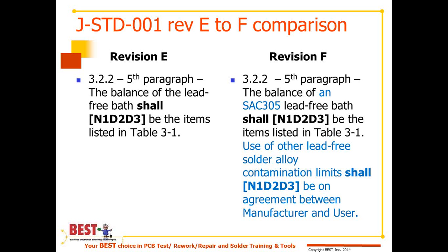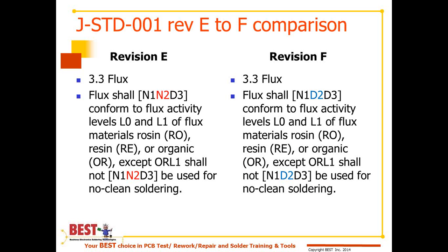The use of other lead-free alloys, contamination limits also, shall be by agreement between the manufacturer and user, and it's a defect for Class 2 and 3 if it is not. So any other lead-free alloys other than SAC 305 have to be agreed upon.